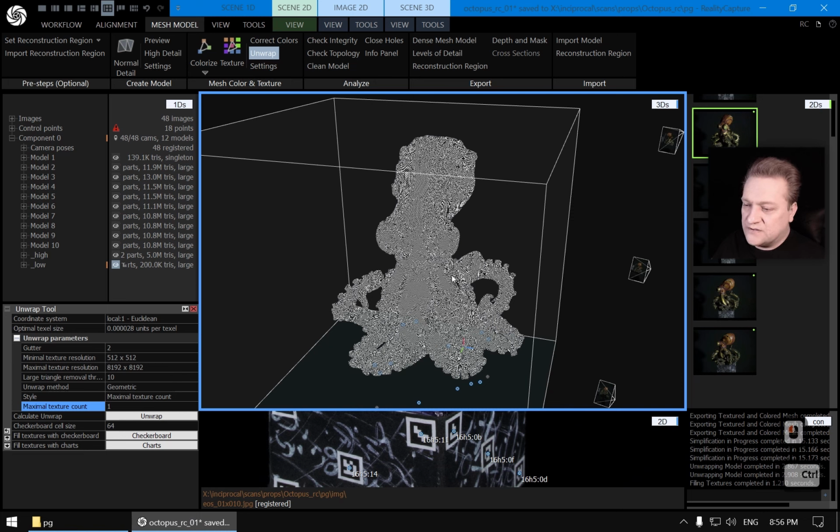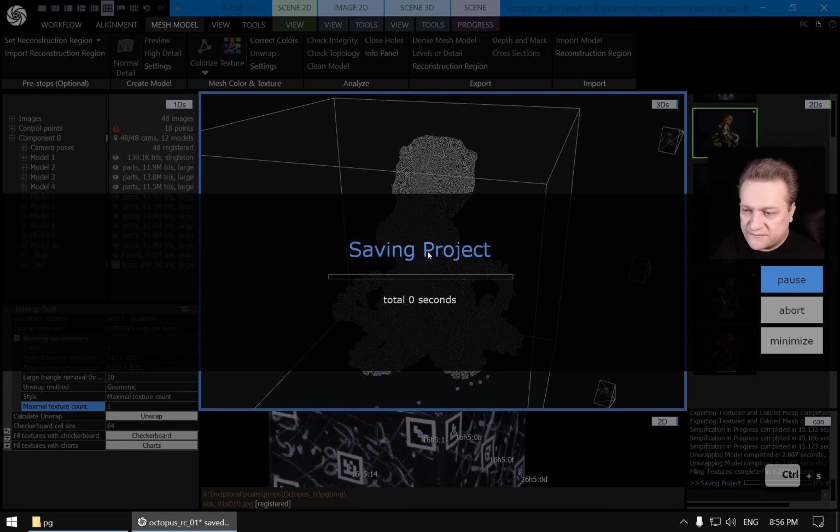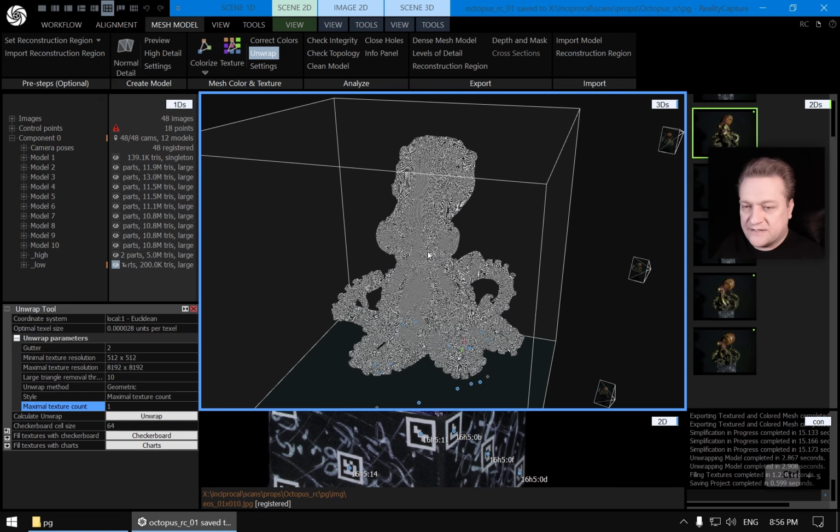Obviously when doing stuff for more specialized things like video games and VFX, if you want to animate something, you might have to use different tools like ZBrush for cleaning and better UV mapping, sometimes user guided, where you put seams, and so you get nice UV charts and things like that. And if you want to animate, you might have to do retopology using quads. In this case, we're just using as is whatever is available in our photogrammetry packages, and that is usually good for any e-commerce stuff where you just render things and don't really worry or care about what the actual topologies are, or UV shells and so on.